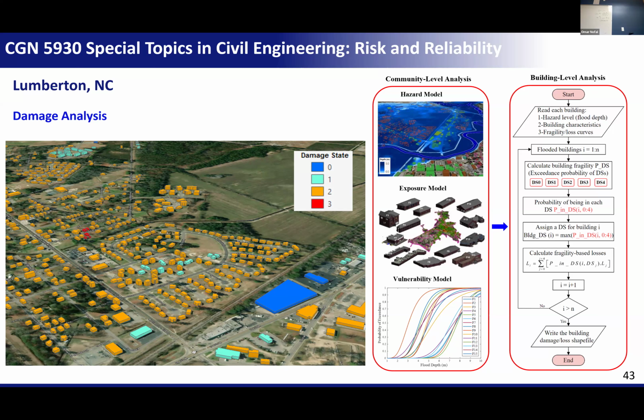However, there are some advances in flood barriers. There's something called bladder dams. It works like sandbags. It's a very thick plastic, like a balloon, and you fill it with water and it gets bigger and it can surround your whole house and protect your whole house. So that's called a bladder dam system. There are other systems like the bladder dam and the sandbag system, maybe you can search online. All these systems, we call building-level mitigation measures.